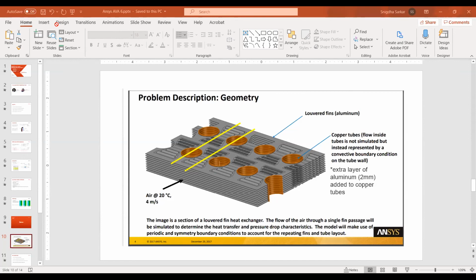At the top and the bottom, we have a periodic boundary condition. And we can use a periodic boundary condition because these boundaries are repetitive in nature. If I switch over to this picture right here, you can see that these are stacked, right? So these are repetitive in nature. Whatever is going in from one periodic boundary comes out of the corresponding point on the opposite boundary. And these boundaries are situated halfway between two successive plates. So that is at the top and very bottom. And then on the sides over here, we have used the symmetry boundary condition.